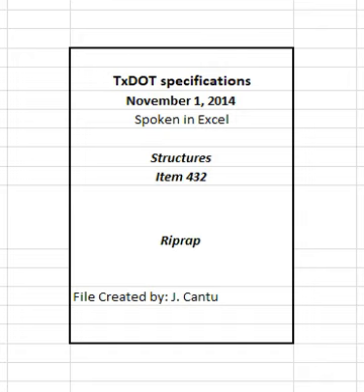Use spalls and small stones lighter than 25 pounds to fill open joints and voids in stone riprap, and place to a tight fit. Place mortar or grout only when the air temperature is above 35 degrees Fahrenheit. Protect work from rapid drying for at least 3 days after placement.